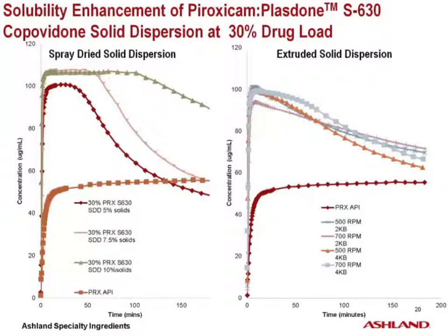During the spray drying process, low molecular weight components such as solvents and API could have greater molecular mobility during droplet formation. Therefore, a higher concentration of API could move to the outside of the spray-dried particle. As seen in this study, a high solution concentration may decrease this molecular mobility during the spray drying process and generate a more evenly distributed solid dispersion with better dissolution performance.